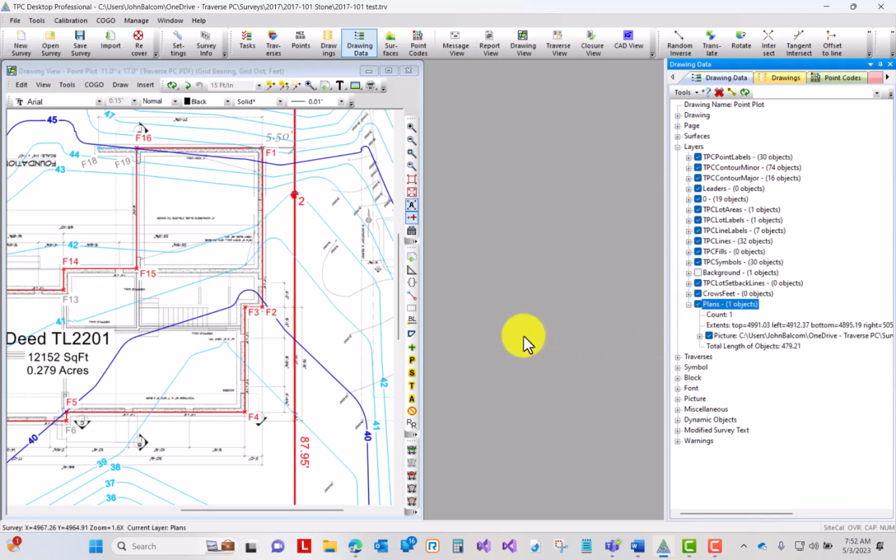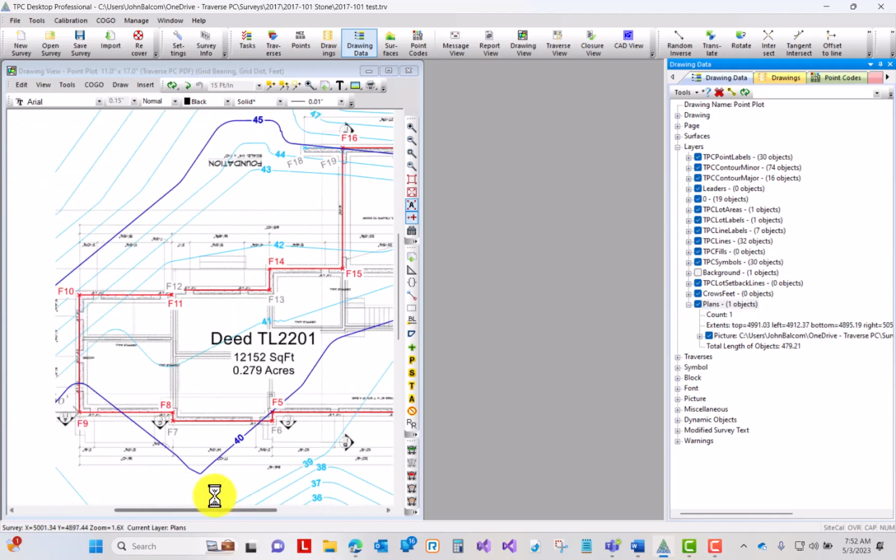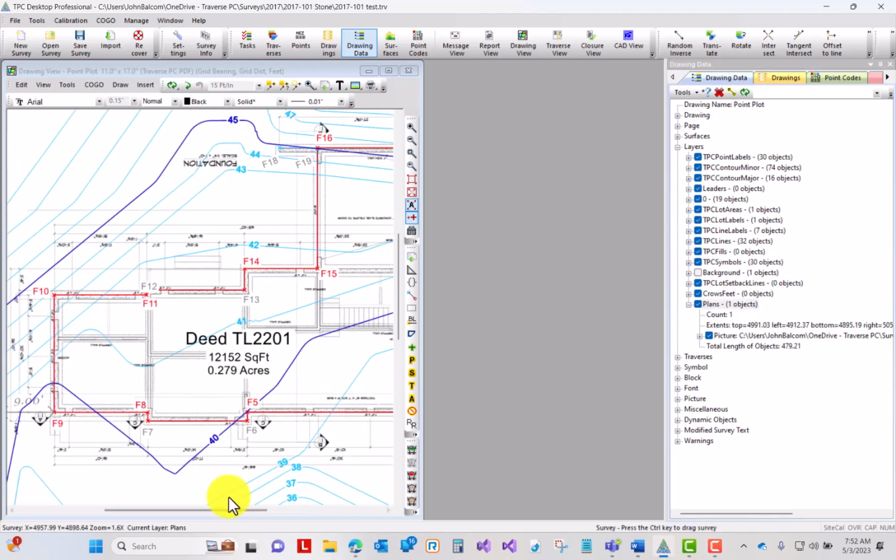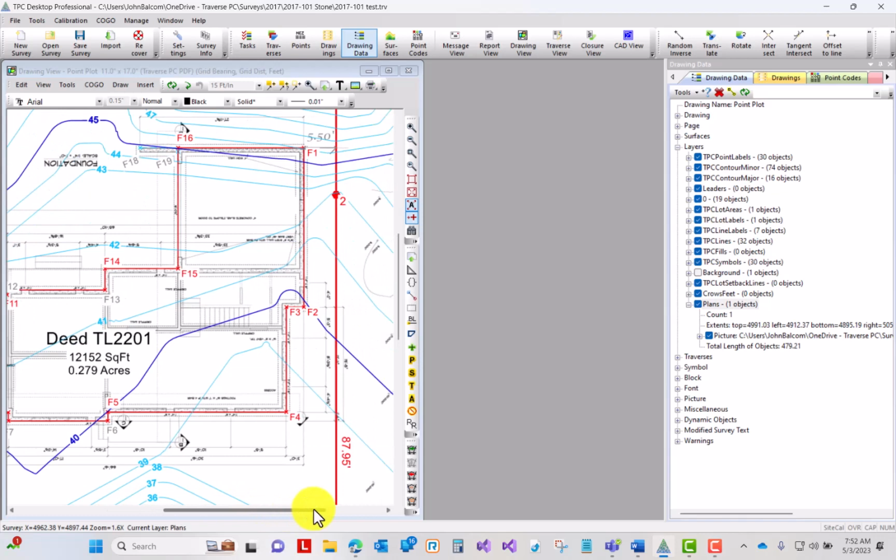And remember now, I'm putting that picture back there because it makes communicating with the contractor a lot easier. I needed 2 additional measurements he didn't give me. And then, of course, when it's all done, I send this back to him, and I just change the color to gray on the hubs I didn't set. So now he knows every hub that I set. I've got a stakeout there with the number on them, and he can hand this printout to his forms crew, and they can go out and start setting the forms on that. Okay, so just wanted you to kind of see how that works with the layers.